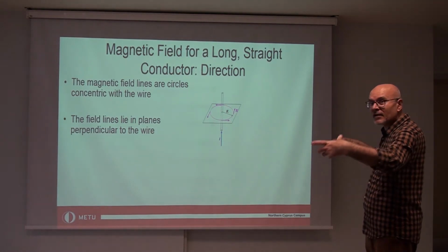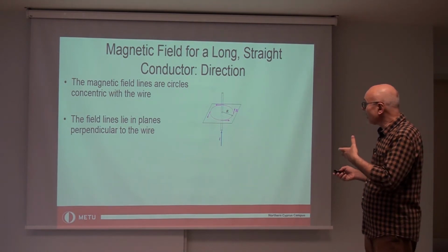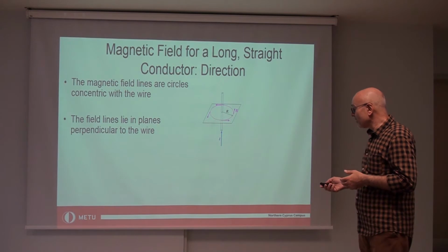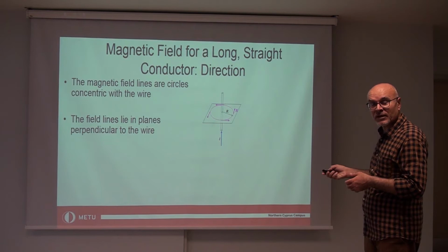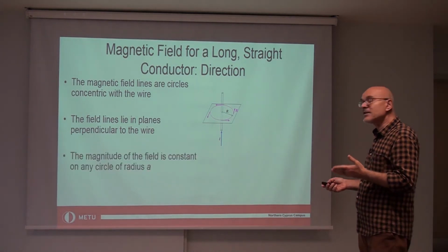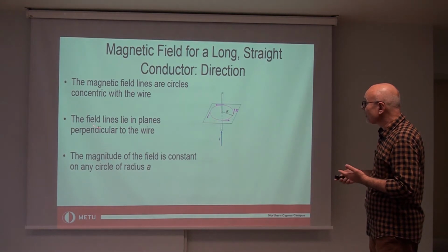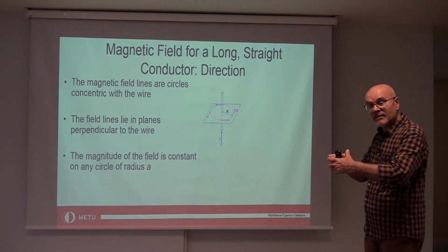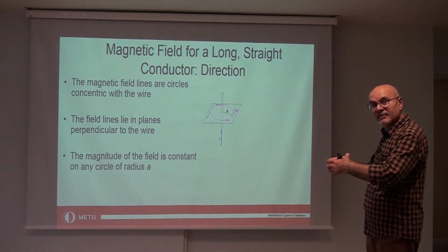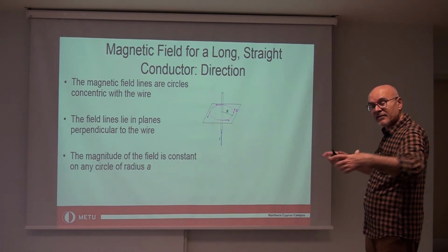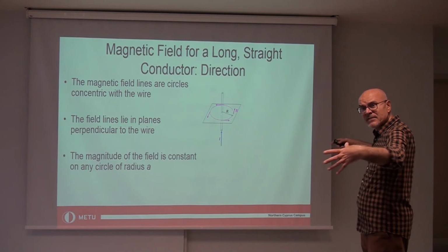Another larger circle, it doesn't make a difference. In all cases, the magnetic field direction will be tangent to that circle. But why in this direction, not in the opposite direction? Okay, because of the right-hand rule. So this suggests to us that the magnetic field lines are circles that are centered at the wire, and they spread from the center of the wire, filling the space.